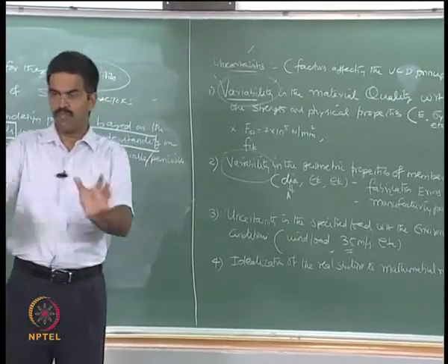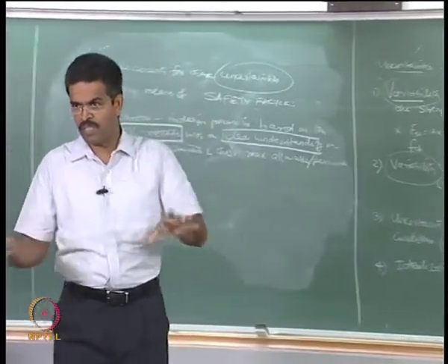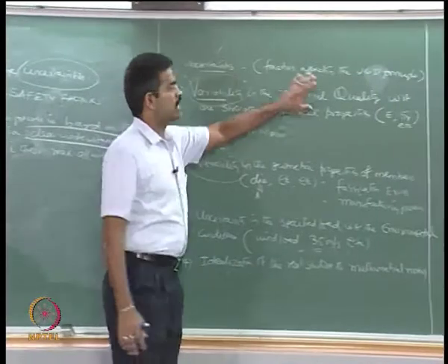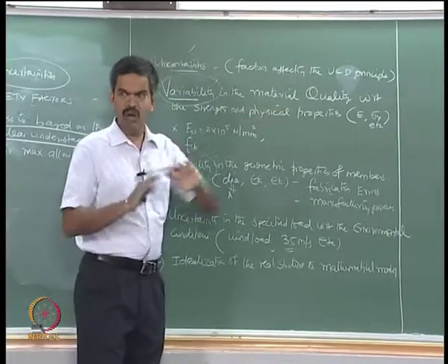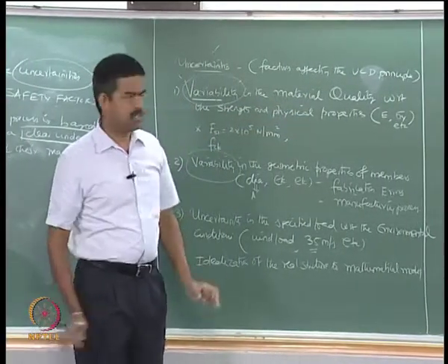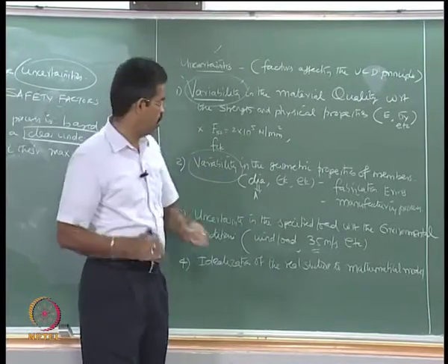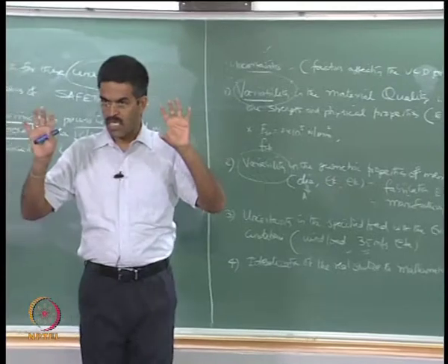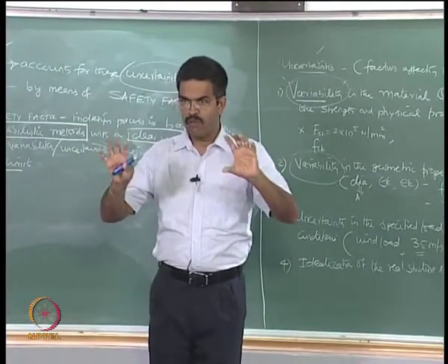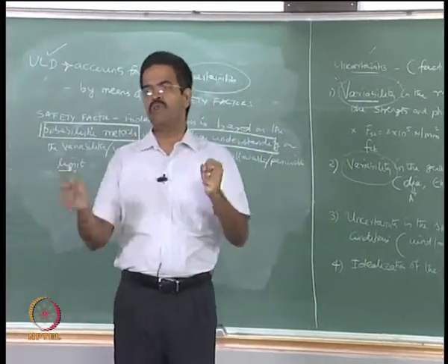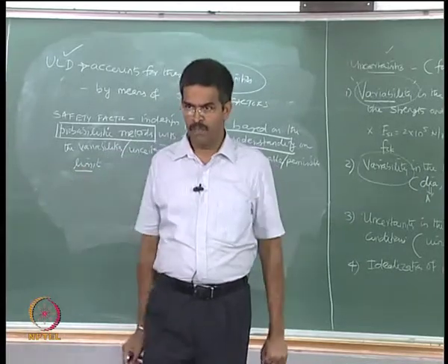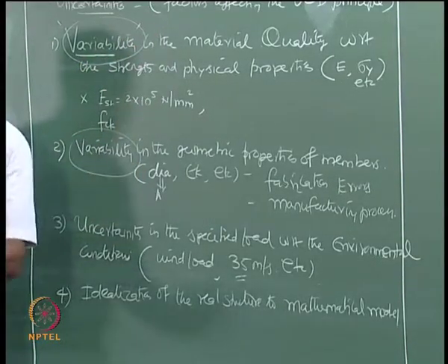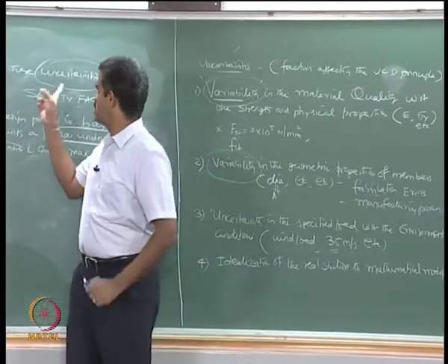So, there are two safety factors independent of each other. The safety factor associated to the strength of the material is not related to the safety factor which will account for variability in the environmental loads. There are two distinct, explicit, unique safety factors which will account for both of them independently. Interestingly, both of them combined together form actually the safety of the system.